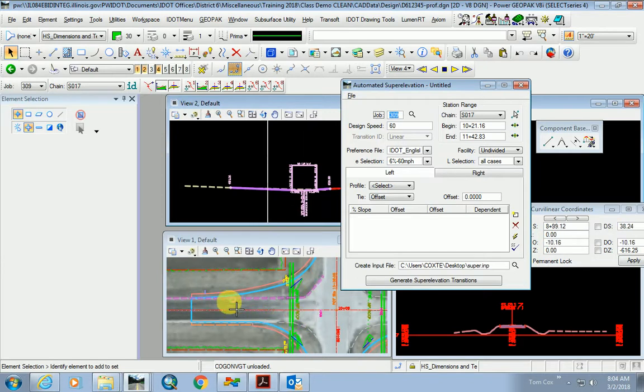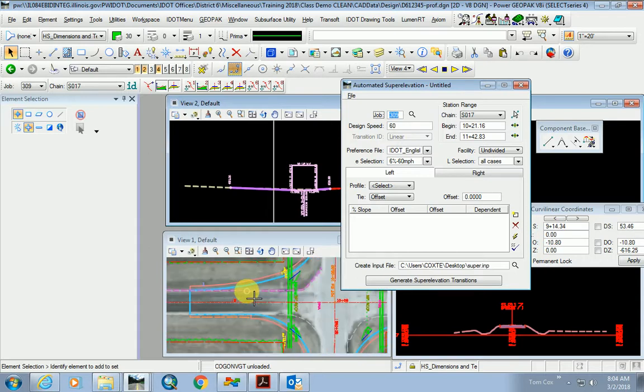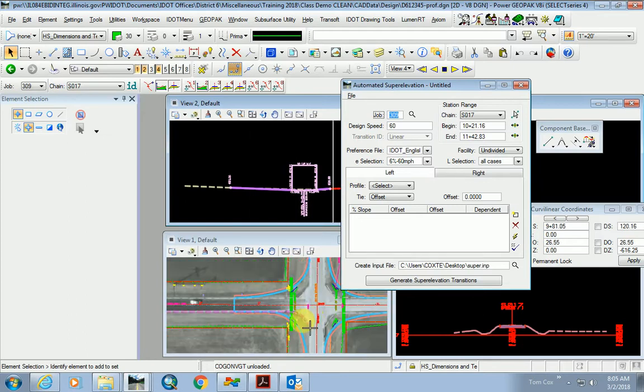In a situation like this, you're probably not going to end up with any kind of a normal crown. You're going to end up warping this to basically match everything around you. Yeah. Especially there, you're not going back. If we were going back further, yeah, you'd probably get into a normal crown situation. But we're really just replacing just this very short distance at the intersection.